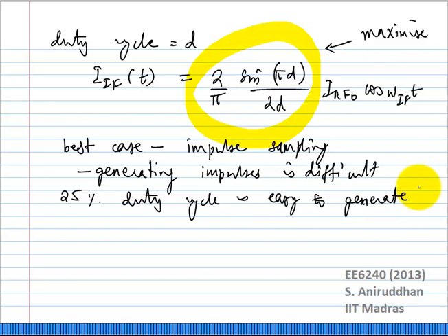So if you have a differential divide by 2 circuit, it very easily gives you 0, 90, 180 and 270 phases. And by an appropriate manipulation of these phases, you can actually create these 25% duty cycle waveforms, and as it turns out, it does give you more gain.